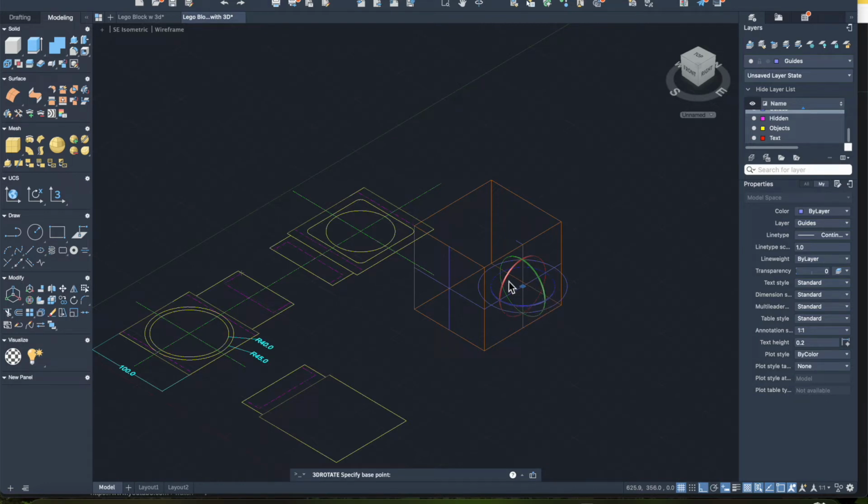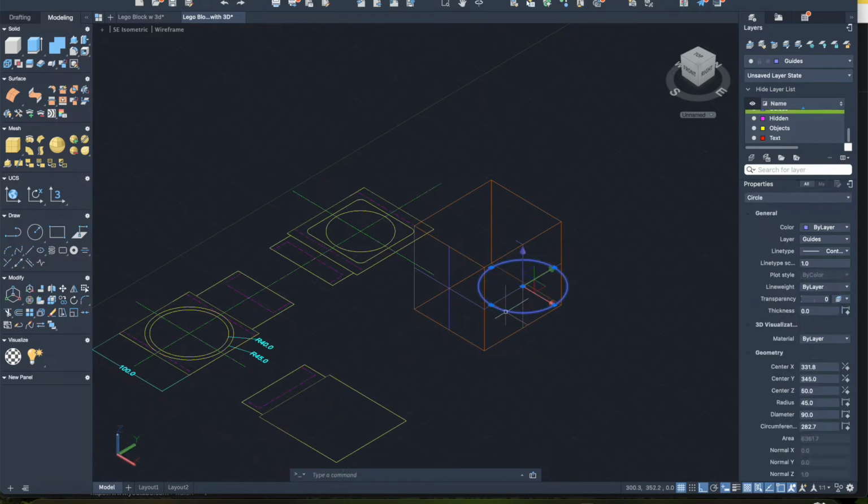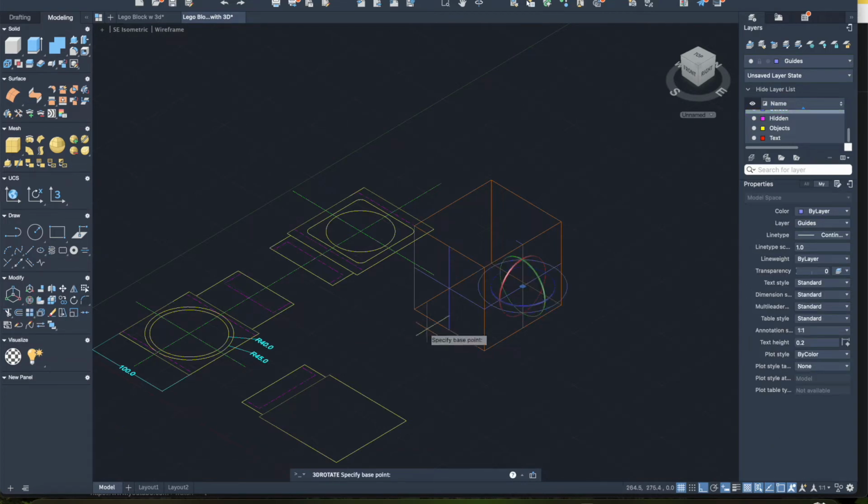This is where it gets a bit confusing because you have the red ring and you have the green ring. It could be a bit of a guessing game, but if you want it to align with the green one and you hit 90 degrees, oops, something happened here. Let's click on here. Bring up the, I'll call it the gizmo. Let's click on the yellow one, 90, there we go. And if I say escape, you can see the circle's in the correct center space.